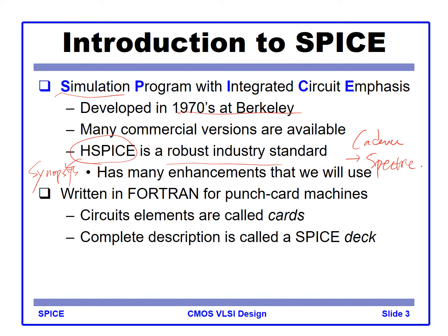In the old days it was written on punch card machines, but nowadays we don't do that. So sometimes we call circuit elements cards, but this is a kind of old term. We usually use a SPICE deck, which is a written description of the circuit. That is called a SPICE deck.